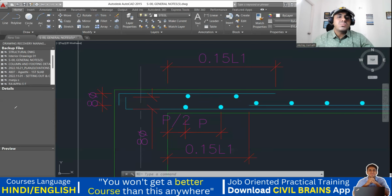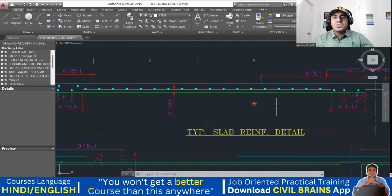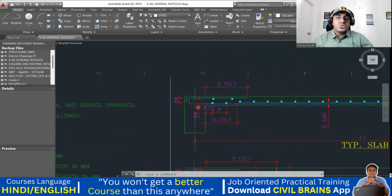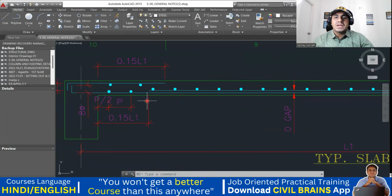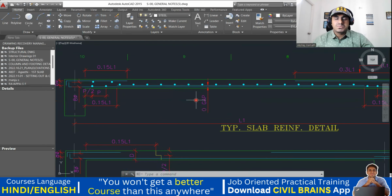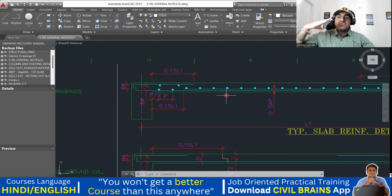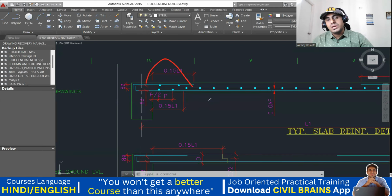Why is it so? In the beam you are doing the same thing, and your beam and slab are similar. Why are you not doing that here? Because I told you that your slab is a kind of simply supported, but due to the small fixity of your slab reinforcement with your beam reinforcement, negative bending moment arises. That is why we get this negative bending moment like this, and that is why this top left extra is given. Okay, that's the first thing.